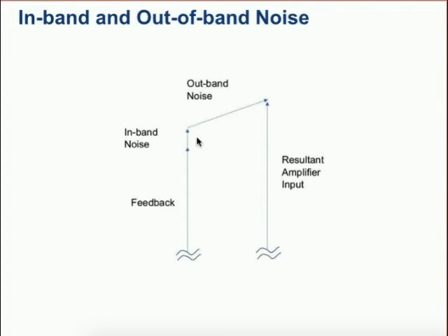So if this noise changes in amplitude or in phase, this whole vector diagram will follow it. This moves 1 degree clockwise and the whole vector diagram will move 1 degree clockwise. And this increases in amplitude by 1 dB and this increases in amplitude by 1 dB. Of course, if we've got a practical oscillator with limiting in it, then of course that won't happen.